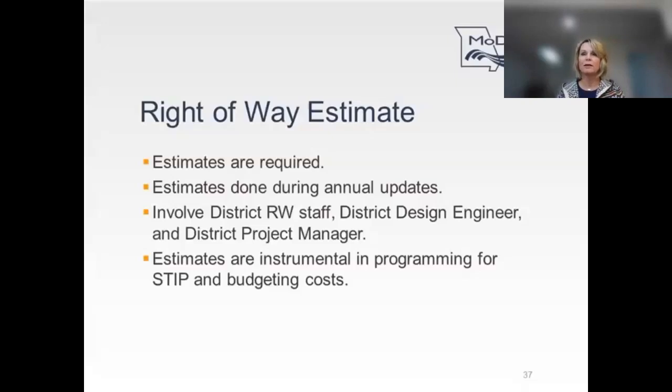This is a more in-depth right-of-way cost estimate that supports additional details derived from a scope and includes specifics such as the number of properties affected, identifying and considering the type of improvements such as homes, buildings, structures, whether relocation will be needed, the type and size of the community using an area trend which determines the more accurate market rate, and whether a property owner could potentially be more complicated to acquire or it involves several entities or LPA agencies or corporations.